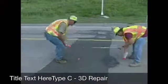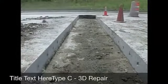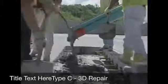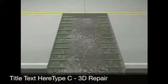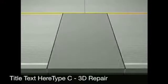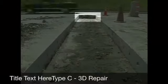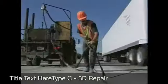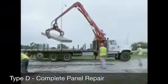Type C repairs involve the replacement of transverse contraction joints. They are used when a small portion of a whole pavement is damaged and needs to be replaced. The first step is the removal of the existing joints. Next, the pavement is sawed full depth on both sides of the repair and along any tied lane. The area is prepared for the concrete replacement and the new concrete is placed and finished. Finally, any cracks or joints are sealed.